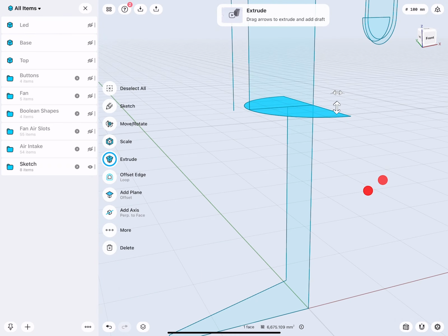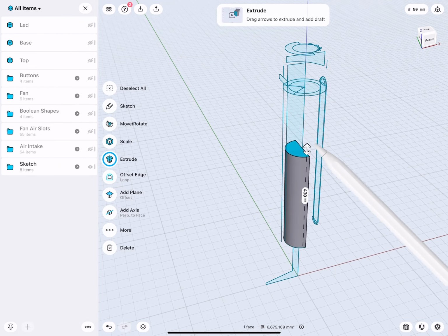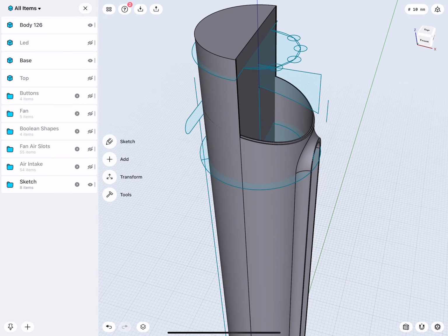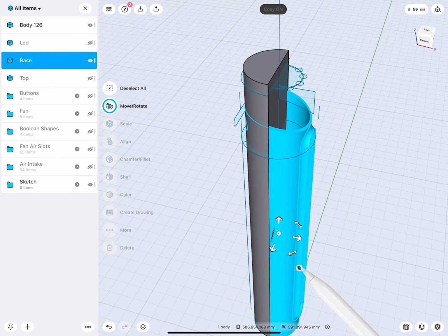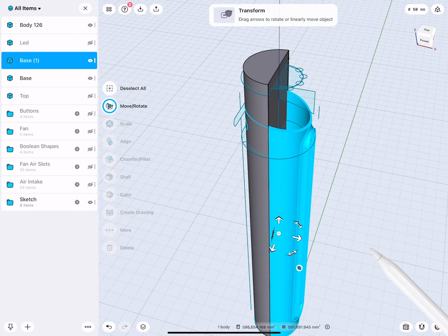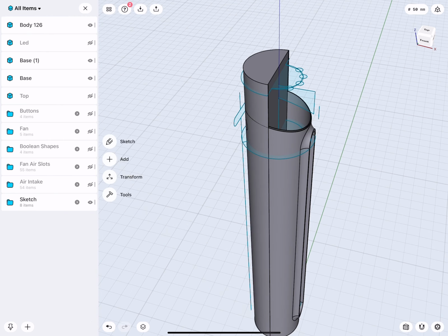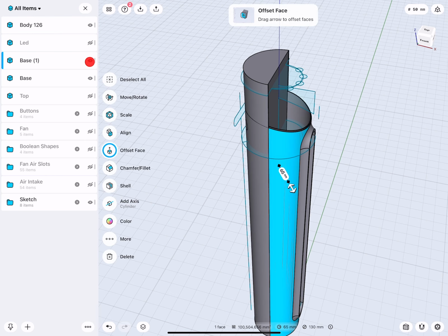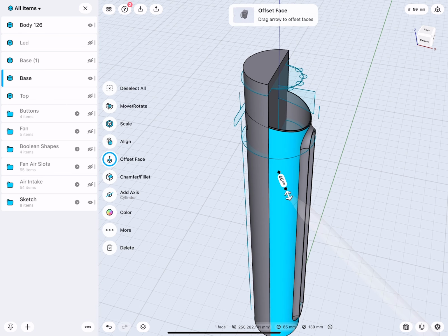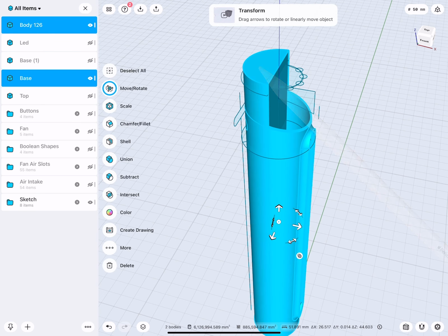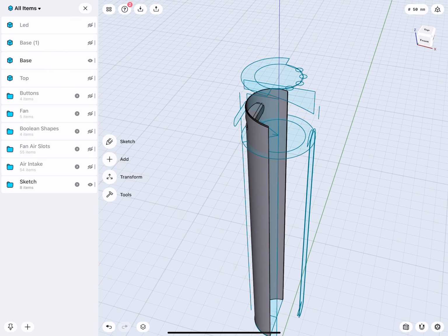So what I will do is I will select the sketch. It's easier when all the objects are gone. I extrude this up really high, make it a little bit bigger than needed. Very good. There is the part. Here again, same trick to make a copy. Move and copy, number 1, minus by U, subtract, keep the removed body. That's right. So this is the base. And we need to figure out actually what is what there. Intersect, very good.